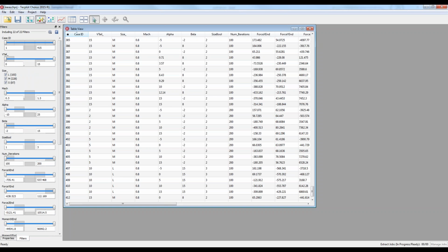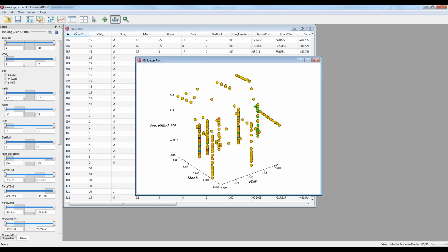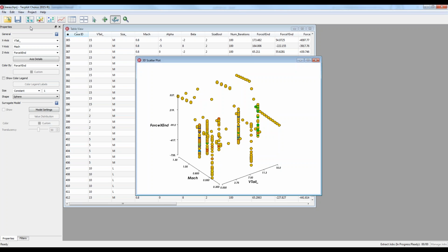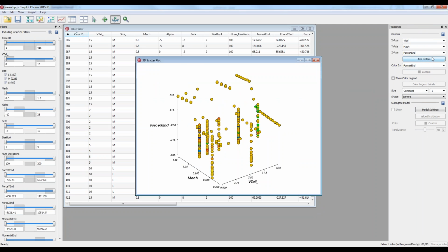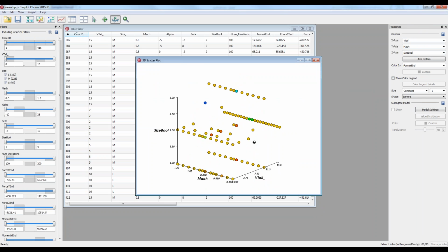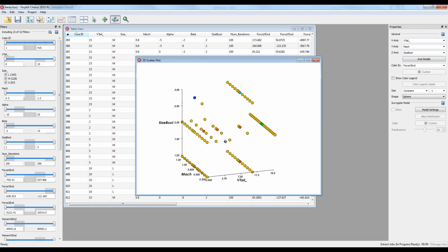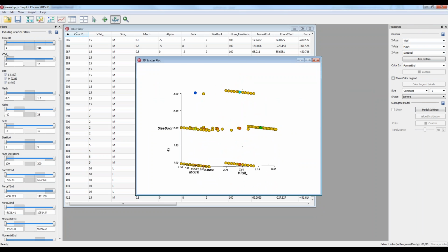And let's start by just looking at the design space. So we're going to look at Mach versus, in this case, the angle of the tail. And for the y-axis, I'm going to move this over here temporarily so you can see both. For the y-axis, or the z-axis in this case, I'm going to use the size Boolean, which is basically the size of the rear wing. And there's only 3 sizes, right? There's 1, 2, and 3 that represent small, medium, and large.